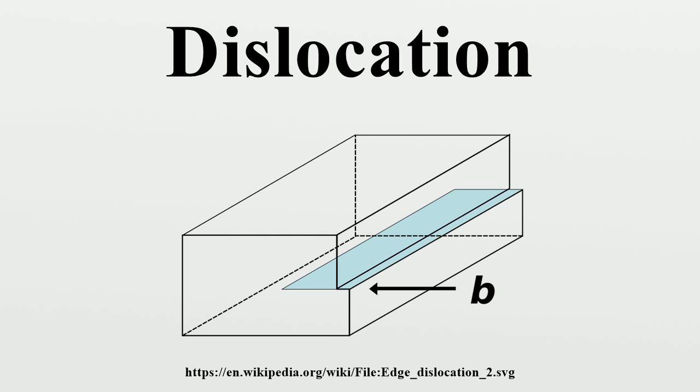Some microscopes also permit the in situ heating and/or deformation of samples, thereby permitting the direct observation of dislocation movement and their interactions. Note the characteristic wiggly contrast of the dislocation lines as they pass through the thickness of the material. Note also that a dislocation cannot end within a crystal. The dislocation lines in these images end at the sample surface. A dislocation can only be contained within a crystal as a complete loop.